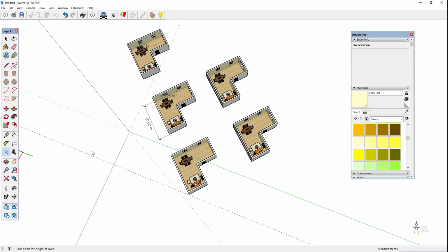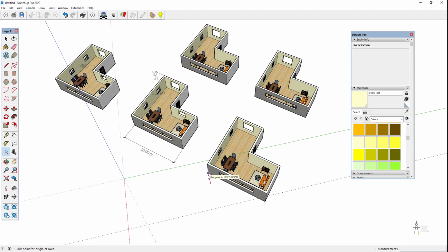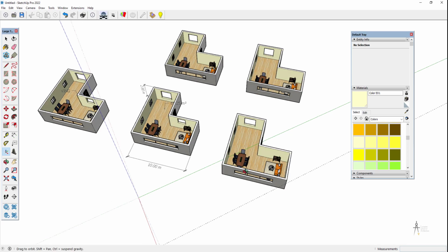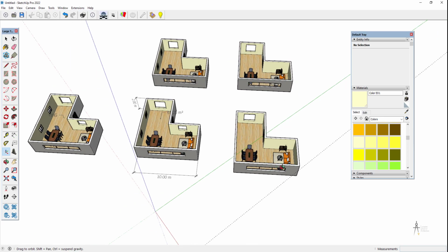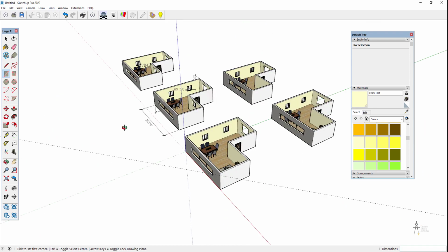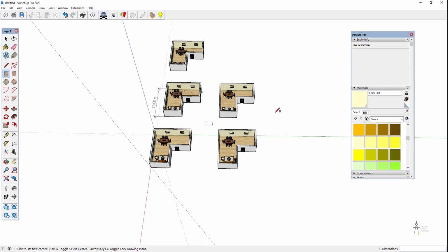There is a way of changing this in the tool that says axis, which basically helps you redraw where my axis is. So I start by clicking on a point, first the floor, the green one, the red one, and then my blue one, and I've redrawn my axis.